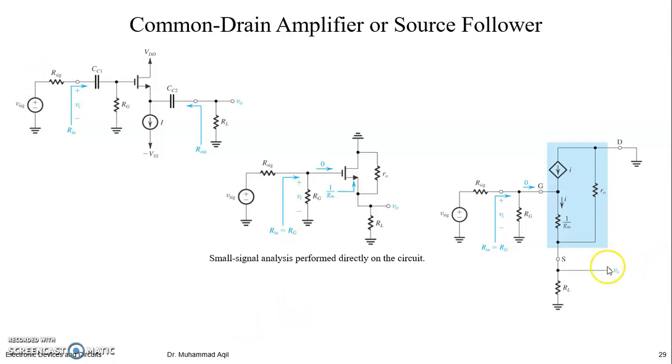So now you can find the relation, the output of this value. How? Vin is the signal appearing across this R input, and Rin is nothing but RG. So Vi is RG divided by RG plus R signal, multiplied by V signal, right? And this Vi will be appearing from gate to ground, right? So gate to ground, okay? And this Vi is then further divided into this resistance and this resistance, right? Series combination of this.